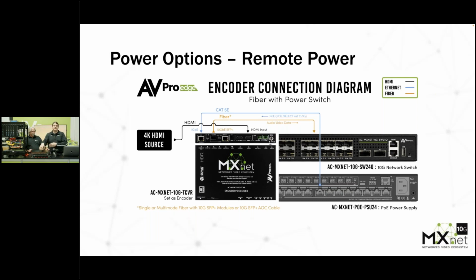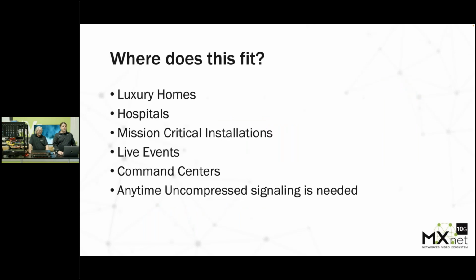So if I combine this with my 24 port switch, now if I run a fiber optic to every endpoint and a piece of category cable to every endpoint, I can remotely power the endpoints through this power. Yeah. So, I like to call it a power injector as opposed to a switch. And the reason is that it's not really a data switch. Yeah, it's not a switch at all. Yeah, it's just feeding power, but it looks kind of like a switch. So I don't want anybody to get confused here. It doesn't do data. Exactly. So yeah, this is just a power injector. That's a PoE power supply.